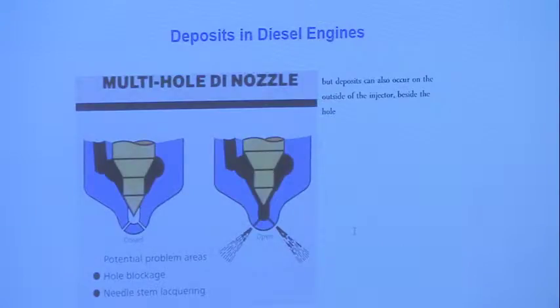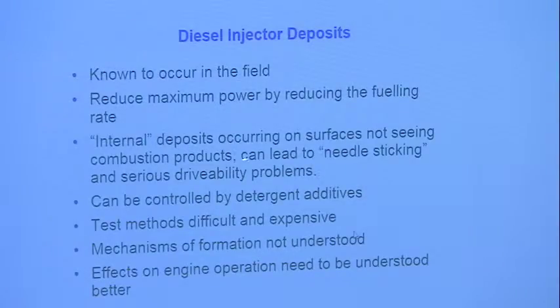And then there are internal deposits occurring on surfaces which do not see combustion products, like inside the injector, which cause needle sticking, and these can be very serious drivability problems. If the needle in the injector doesn't move, you just don't have any control over it. In fact, sometimes there won't be any fuel. There have been massive instances in southern Europe where diesel cars and trucks were just coming to a stop because of this problem.